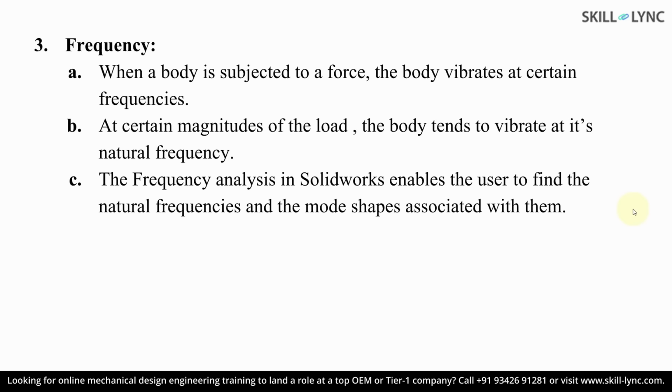In the frequency model, we'll be able to analyze a model which is subject to a force and the body vibrates at a certain frequency. As we all know, every body has its natural frequency, and this natural frequency can be found out by using this frequency module. From this type of analysis, we can look at different mode shapes associated with the model.